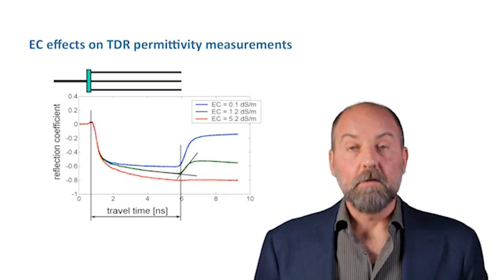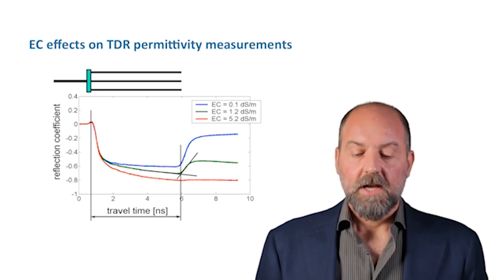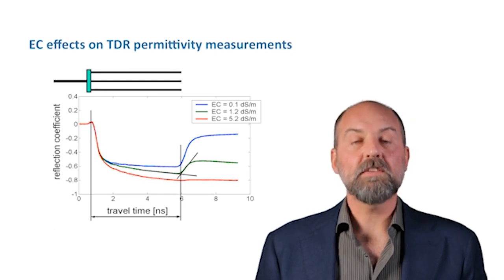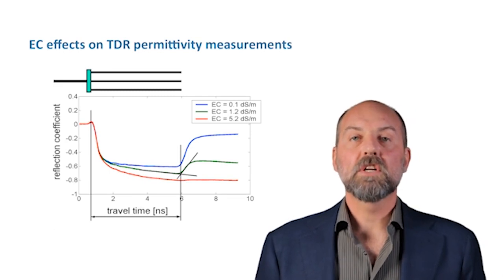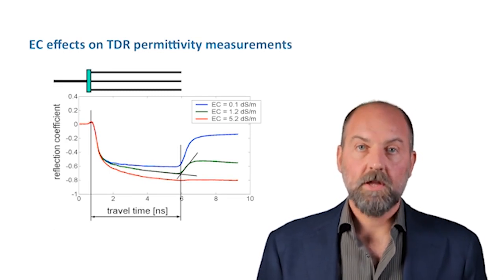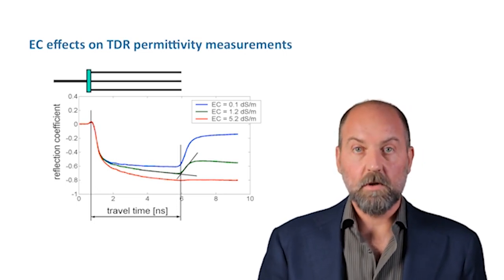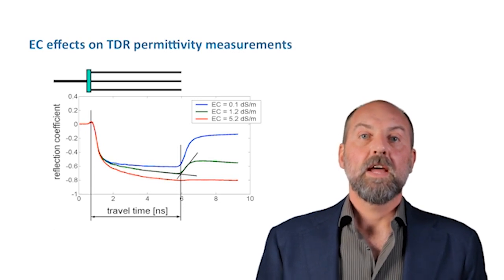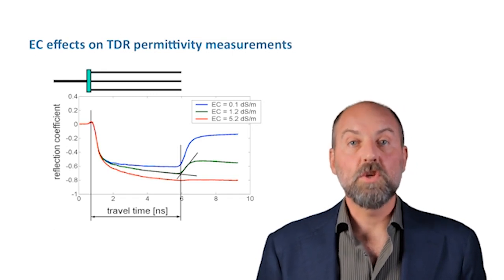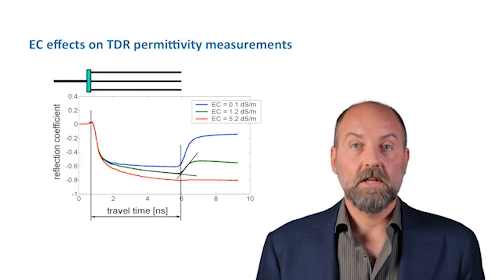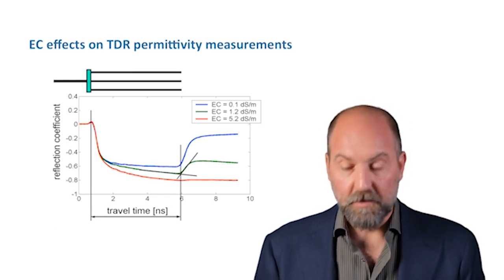Another important aspect that needs to be kept in mind is that as the conductivity of the system becomes larger and larger, this signal undergoes energy dissipation. And this is the case simply because as the signal, as a voltage, propagates, if the system is conductive it will eventually induce electric current. And it takes energy to have an electric current. All this energy eventually is dissipated from the signal.